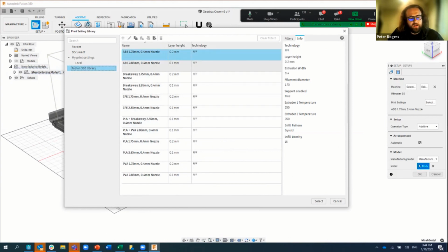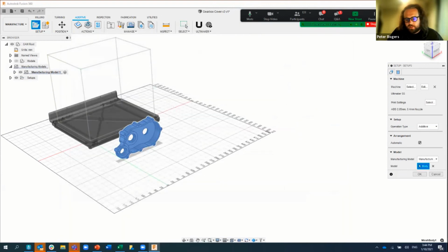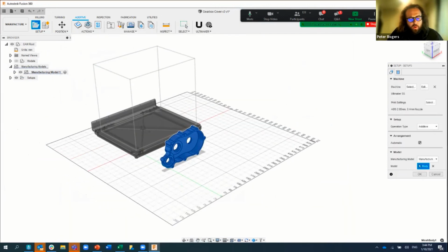be doing it a bit thicker, I could actually say, well, I've made the effort of creating these curved surfaces, filleting it. So I want to actually represent that a lot more nicely without having those relatively ugly looking steps on some of those edges, which you'd probably see with the FFF or FDM methods. So I'm just going to select a 0.1 mil layer height. It's going to add a little bit more to the build time, but I'm more interested in catching the quality.